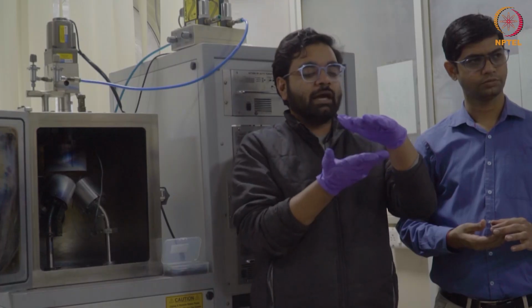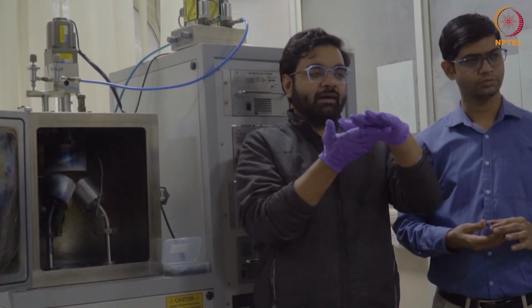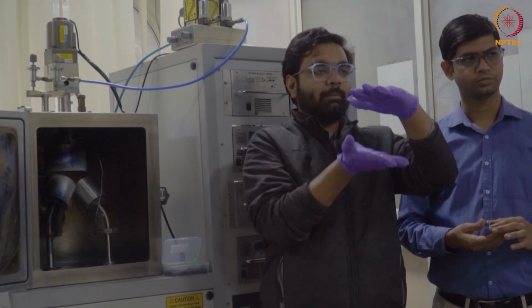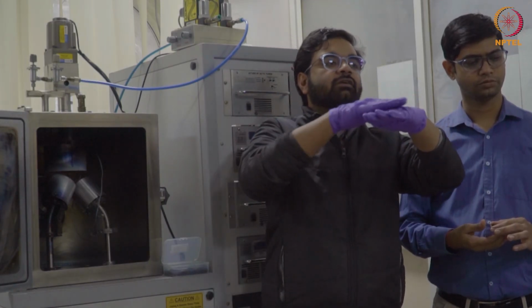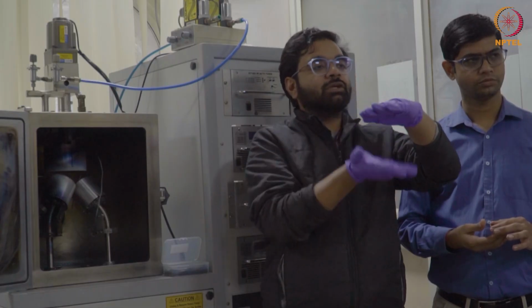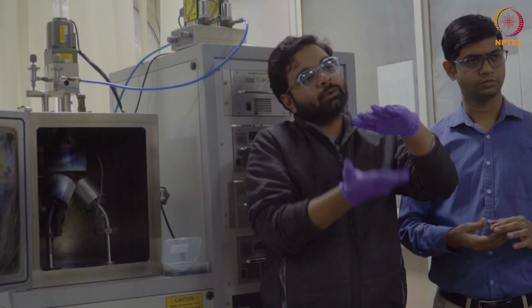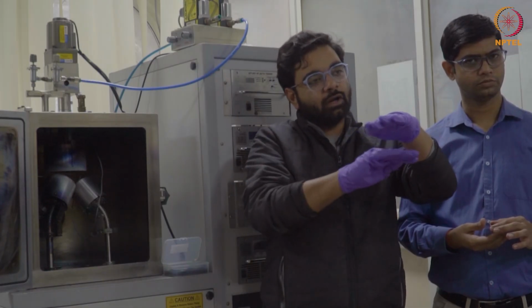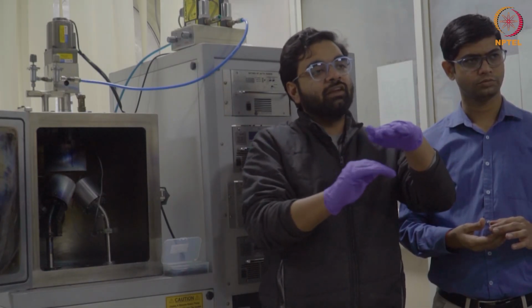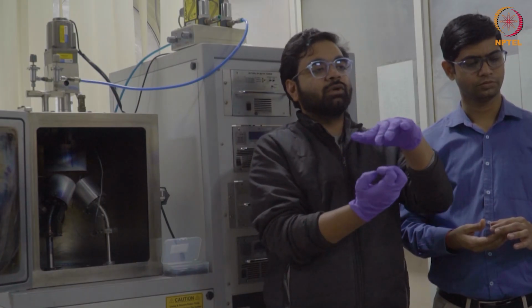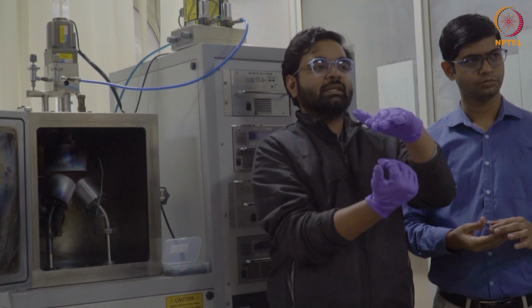Now for the gas pressure to release, it might have to either go onto the front side or it might go on the back side. Now the back side of it is a solid silicon substrate. So it won't allow the gas pressure to go on the back side. So what will happen? The gas pressure will automatically have to come on the front side. The front side of it is what? It's a coated thin film. This thin film won't hold that gas pressure because that gas pressure is very high. So it won't hold that gas pressure, and it will eject the material from the surface.